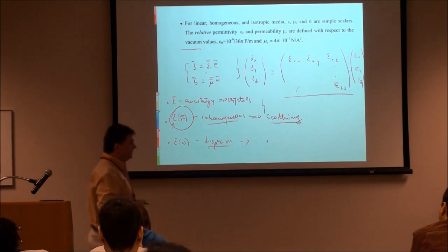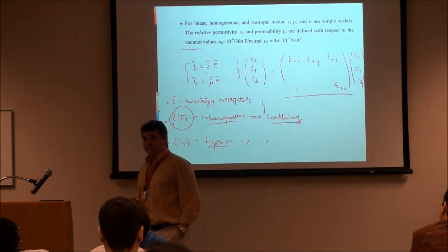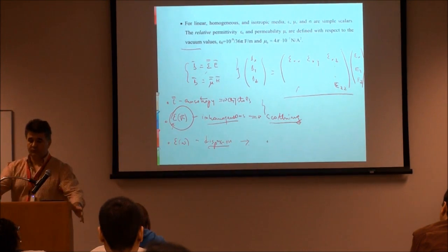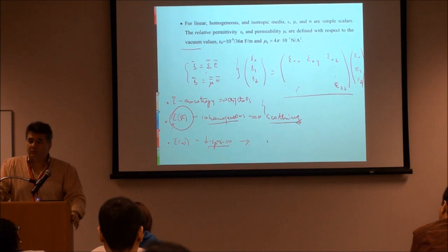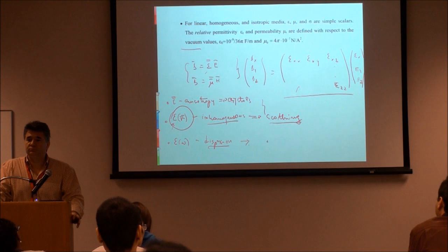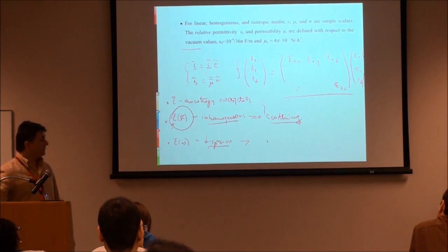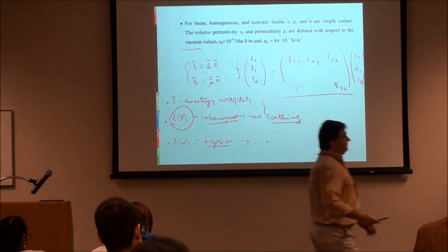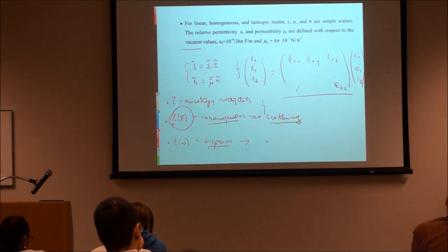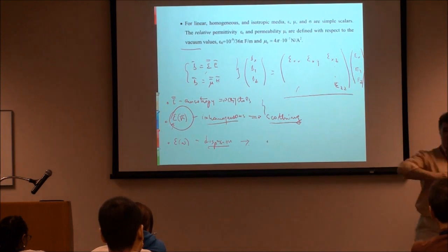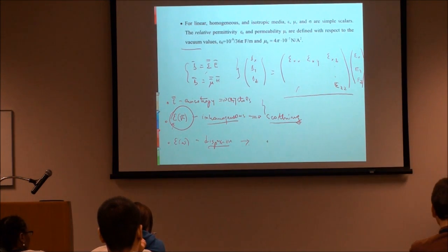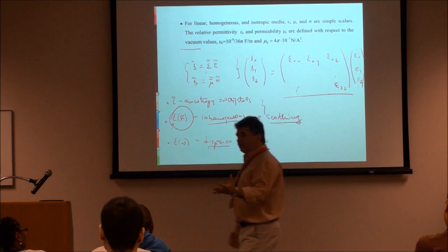Now, where is that useful in imaging? First of all, let me ask you in the time domain. Why is dispersion important in the time domain? What can that do? Pulse spreading. So you see, even if I start with a very tiny pulse, what I get on the other end is a spread out pulse. And believe it or not, this spreading comes from the fact that H is a function of omega. It is due to dispersion. So can you think of an example where that's crucial?